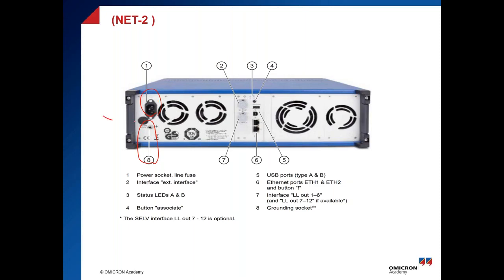As you can see here, we have a fuse, and that fuse sometimes, due to some problem with the connection of the power supply, can blow. Before starting troubleshooting, you have to check this fuse. If it is blown, please try to replace it with one with the same specs as in the CMC.